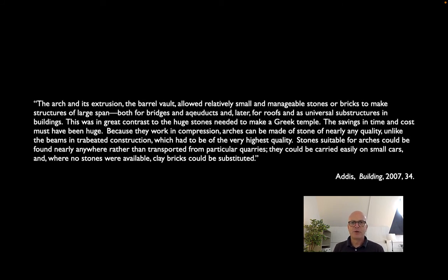Bill Addis, in his book Building, makes very clear that he thinks this is one of the great kind of leaps in human construction, that the arch and its extrusion, the barrel vault, which we'll talk about here in a second, allow you to make long spans out of small elements. In other words, you don't need to go find a giant tree trunk or a giant piece of stone to bridge a span. With these techniques, as we'll see, you use a technique called centering that allows you to build an arch or lintel out of small pieces, out of bricks that can be brought to work by hand.